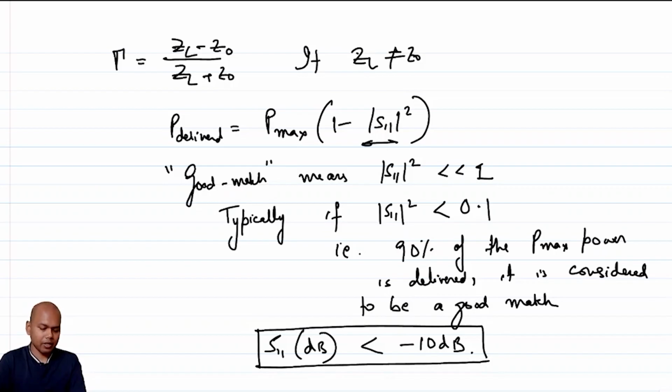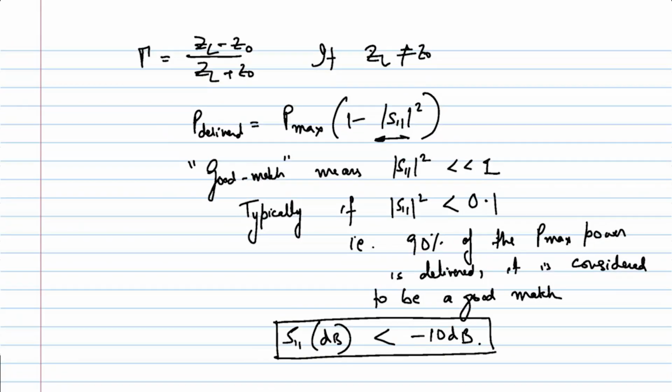Right? So that's why, if you see any data sheets or read any papers, often the idea of a good match is that your S11 should be less than minus 10 dB, right? Okay. The next thing that as designers we should be cognizant about is